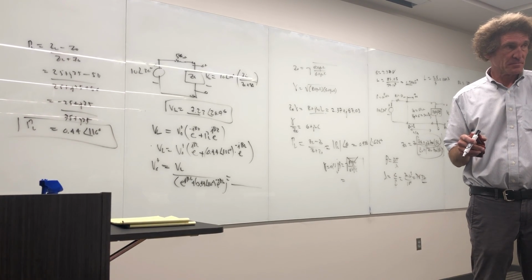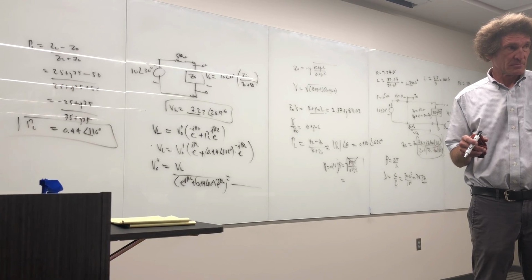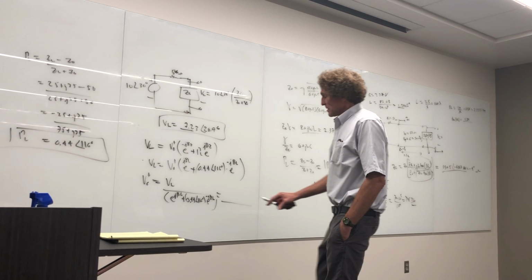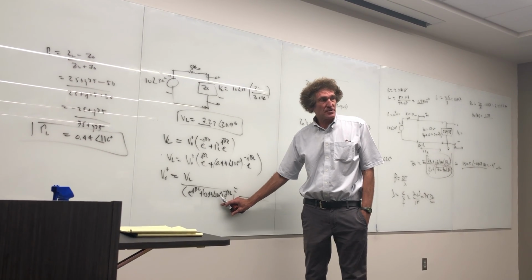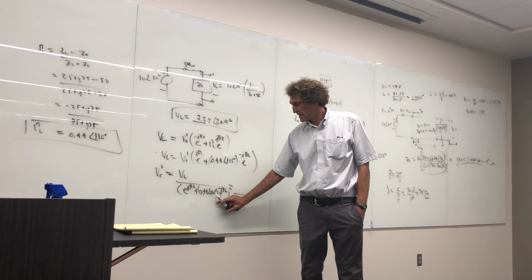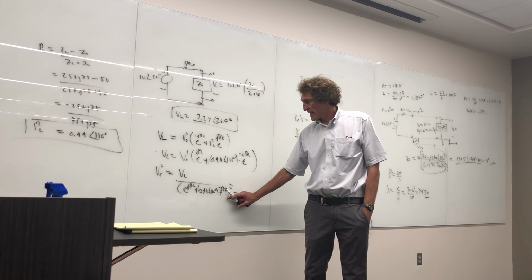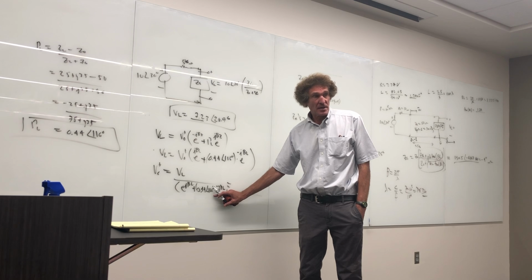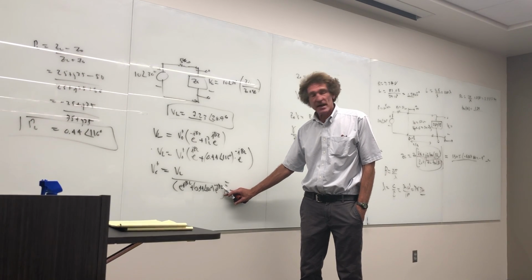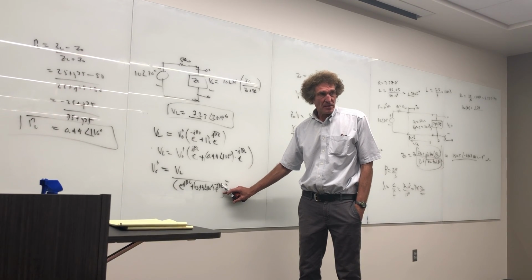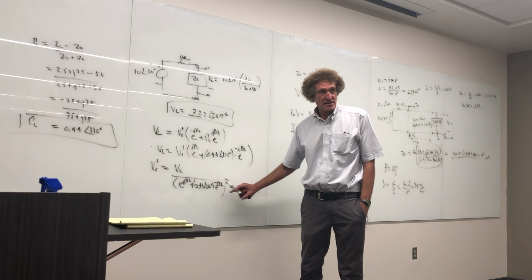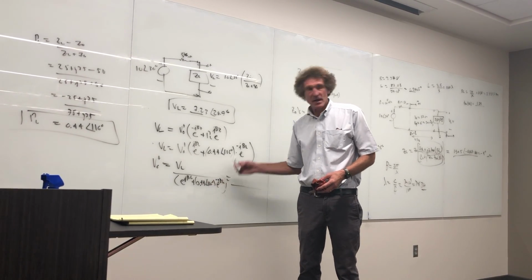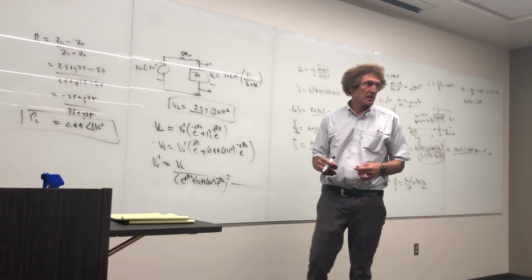Ivan, you got it? What's the problem? Yeah, E. This is simple. Turn this into radians right here, just 1/16 into radians. Now that's e to the j, whatever it is in radians, right? Take that and subtract beta L from it, and then put it up here as e to the plus j that. Right? That's the easy way to do this. This is usually the part I think people are going to get stung by. They're not sure what to do with that.